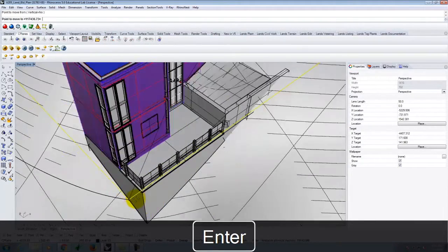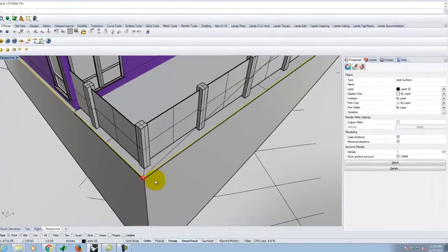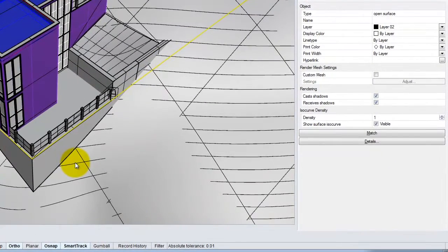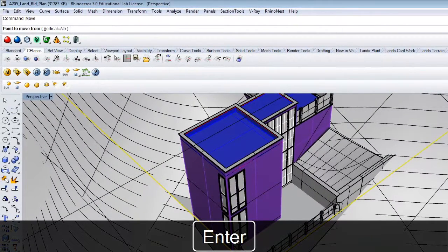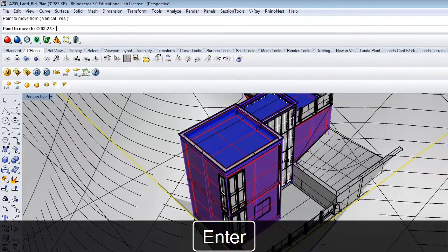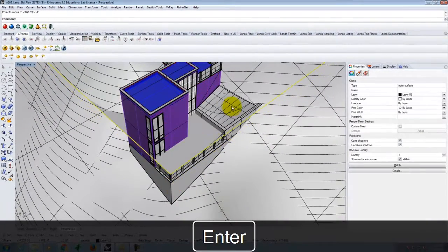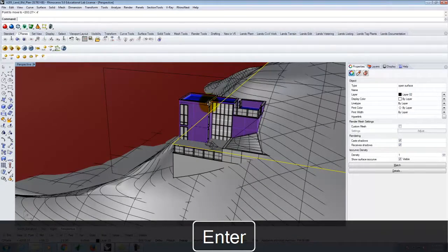And typically speaking, a plan view is always at 4 feet above ground level. And we do the 4-foot mark because it's above kitchen cabinets, so we can see the counters and the sink and stuff like that. But it's below the upper cabinets in the kitchen, so we're not cutting through those. So that generally cuts through all the windows, cuts through the doors, etc. So I'm going to go ahead and move this giant plane here vertically by 4 feet so that it cuts through my building at that ground floor.